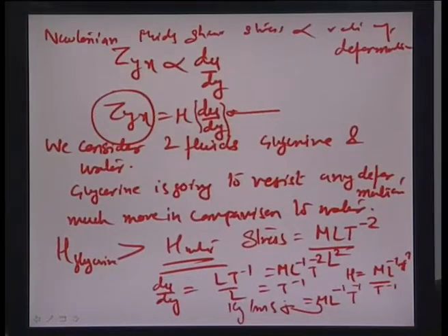In fluid mechanics we seldom use these units of viscosity. We rather express viscosity as a ratio between the absolute viscosity and the density, which we also know as kinematic viscosity. This new term is used very often in fluid mechanics, and it is obvious why, because there may be substances where density is higher and so is the viscosity.